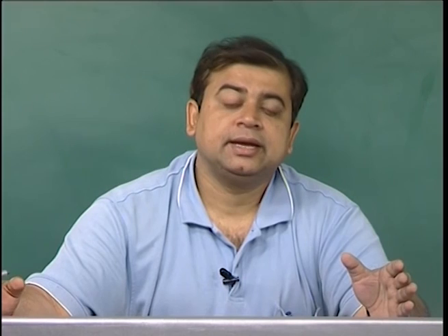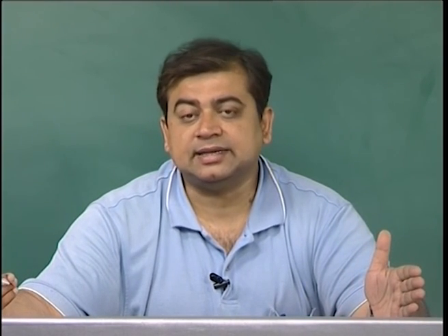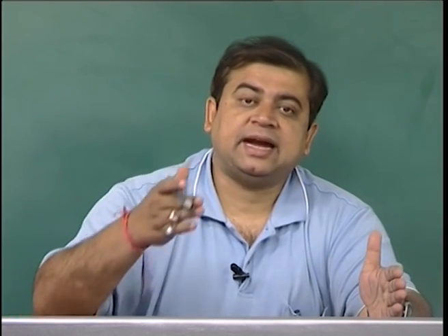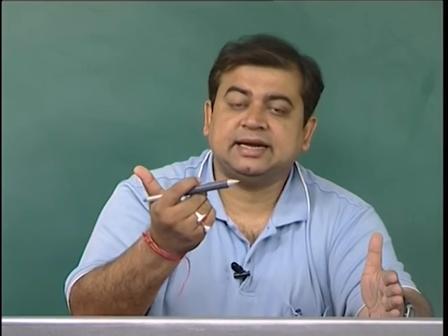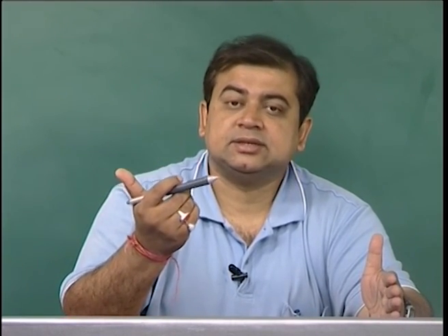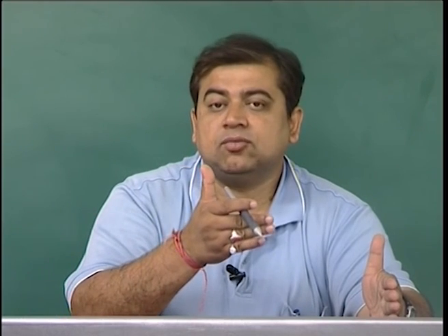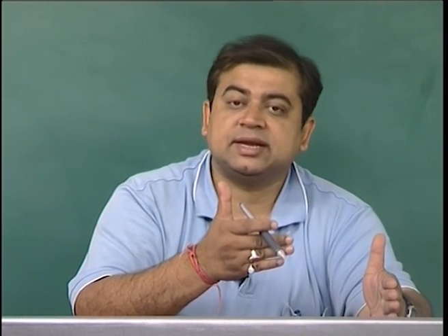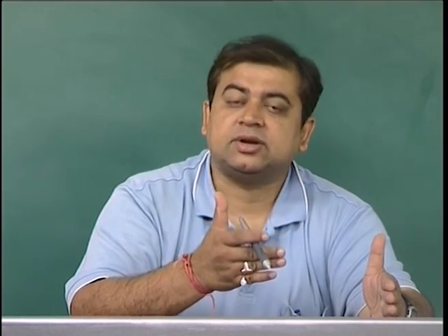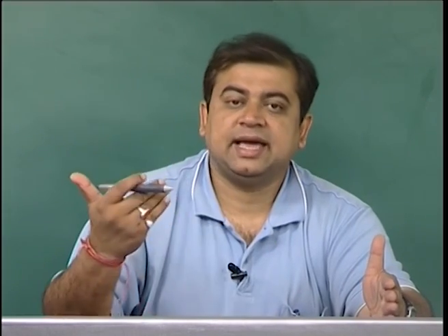So therefore it is actually the x direction in a right handed Cartesian coordinate system, and the flat is always perpendicular to the x direction, and that indicates the other directions of the crystal. So in comparison to that flat, you can record what is the 111 direction or 110 direction or 101 direction or any other direction with respect to this x direction.